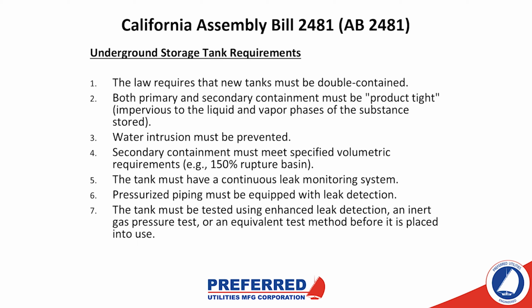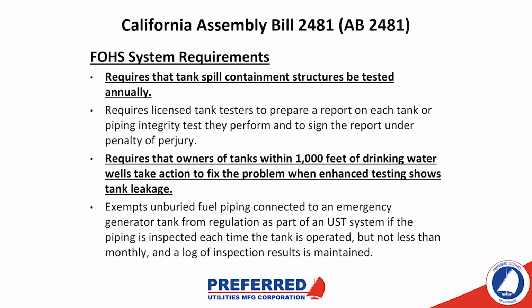Number 7, the tank must be tested using enhanced leak detection and inert gas pressure test or equivalent test measures before it is placed into use. Again, I had discussed the former ELD method that is no longer used. This changes periodically, but these days it's quite simple. Pipe pressure test, special gas is often used, and the piping itself and the secondary can be tested with those particular methods.